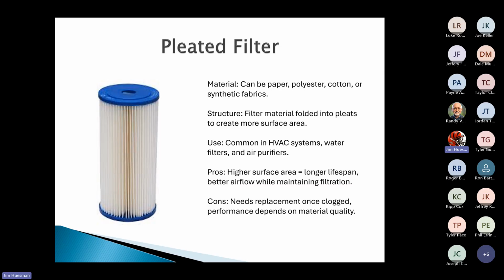So as the water is passing through all of those pleats, we're actually catching all of that debris down in the pocket and also up the sides and down. So we've given it a huge surface area that we're able to catch any of this debris that's coming through the line. Now, I'll tell you, with any pleated filter, really what we're doing is we're just trying to get any sort of extra debris out of the line, any sort of sand, just debris. I hate to use dirt, but it's in our water lines.